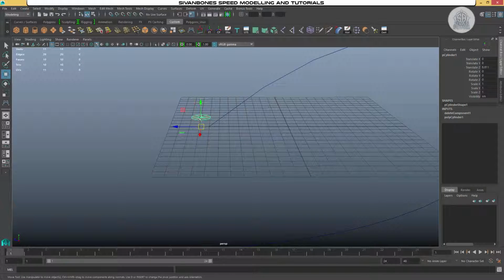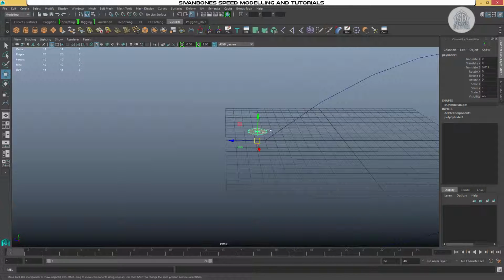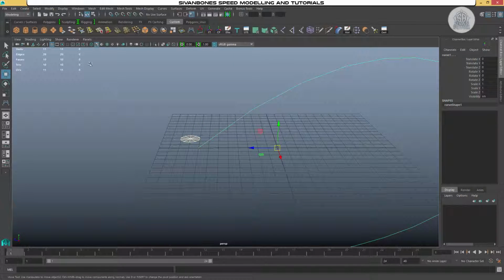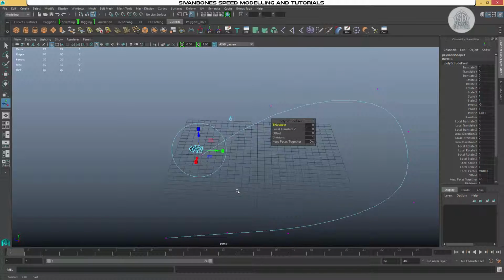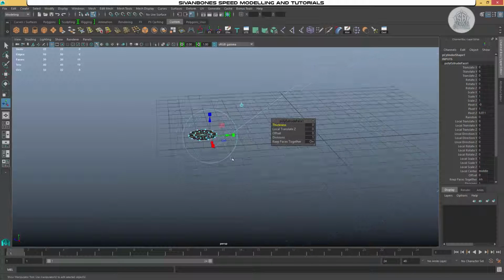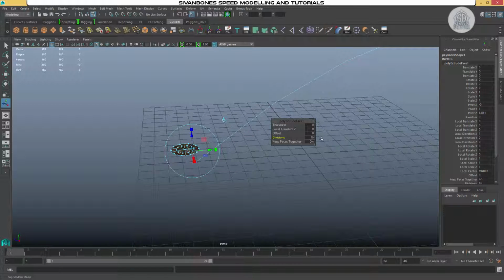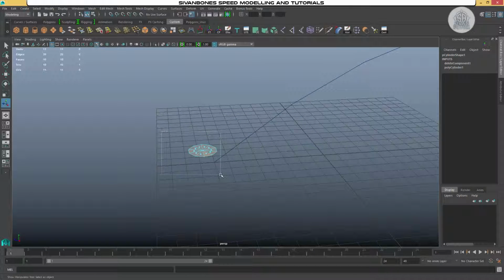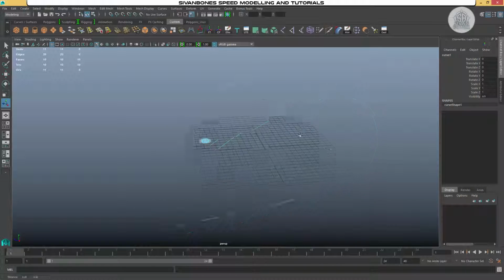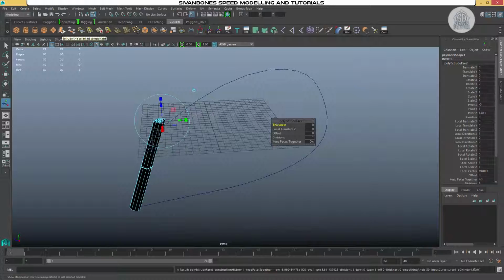Right, the way it's different from previous versions is you used to be able to just select the geometry, select the curve and hit extrude, and it would do a basic extrude that you would then edit after. It no longer really does that. Even if you increase the divisions, it doesn't do anything. What we have to do now is select the object in face mode, select all the faces we want to extrude, then select the curve, then hit extrude.